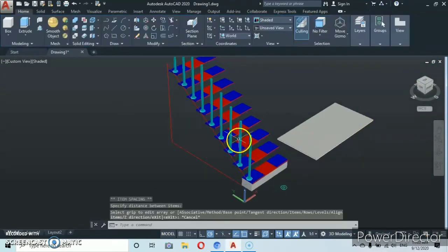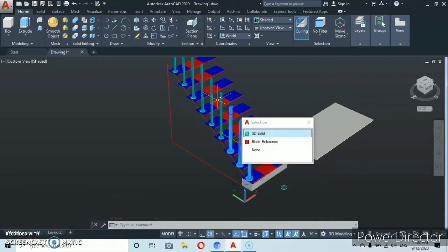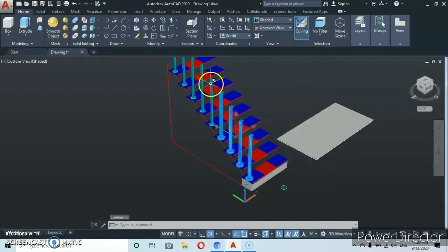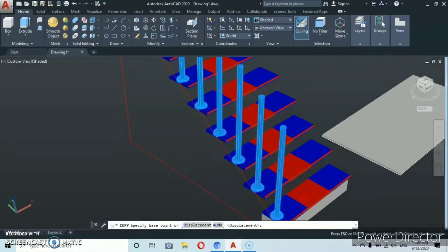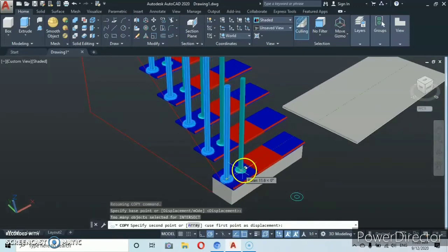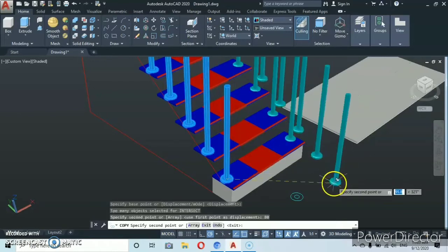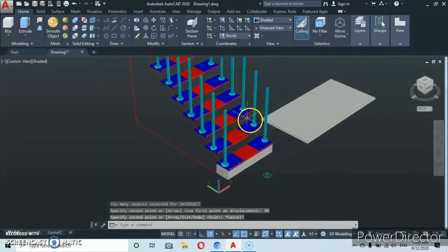So from here now, I'd like us to select all these members. Let's just select all the bars and let's create copies. Then let me zoom it so that you see so well. Then you come here and make sure you snap at the midpoint. You click, then you move it on your right and you type in 80. Enter. So you're gonna find something like this.